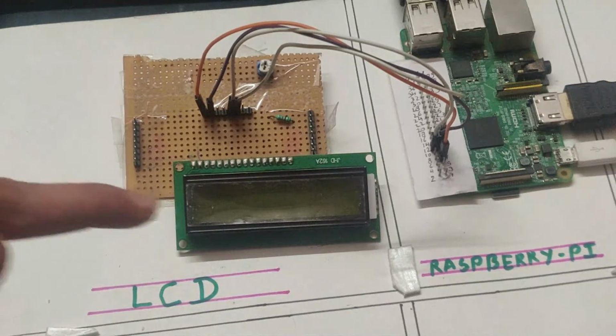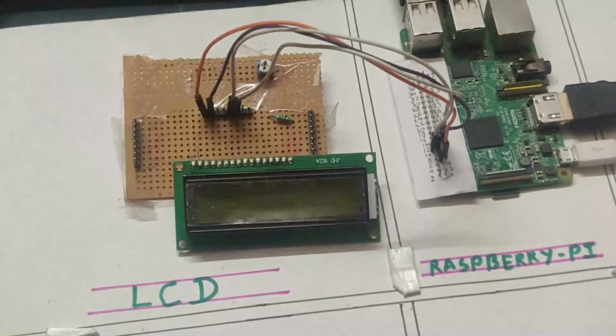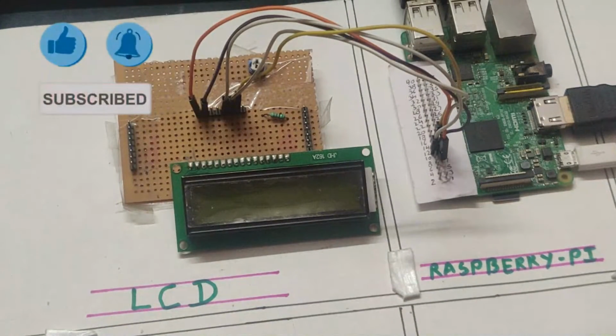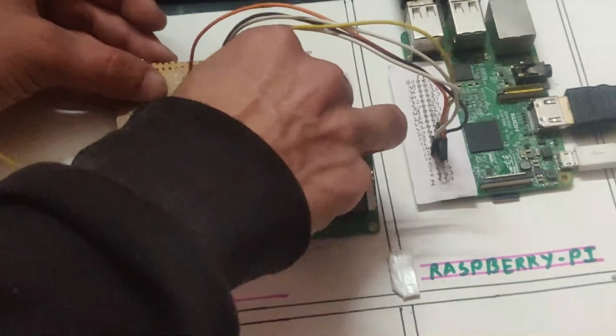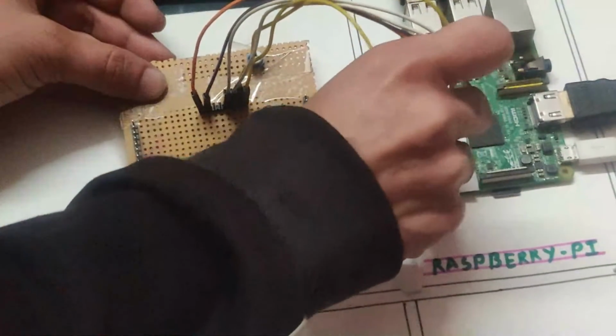After that, the D6 pin should be connected to Raspberry Pi pin number 15. So D6 of the LCD should be connected to Raspberry Pi pin 15. Then after that, the D7 pin should be connected to Raspberry Pi pin number 16. So D7 should be connected to Raspberry Pi pin 16.